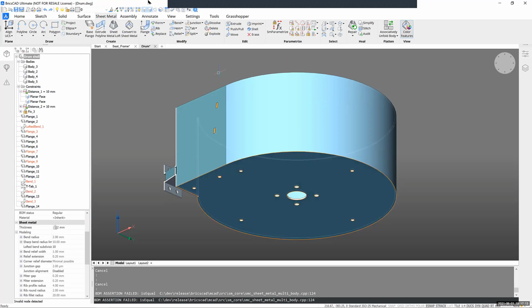How do we do this? We go to the modify option, and then you see the tab. It's underneath the junction. You have an option tab. If I open up this option, you see create array tab, and I click this one. And now it will ask me to select a junction or curved hard edge to create an array tab, or we do the inverted curved tab, or a single tab.